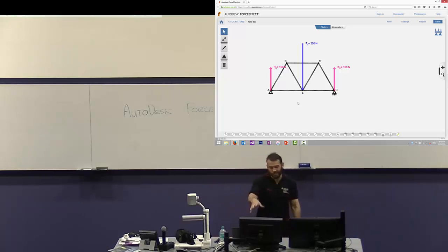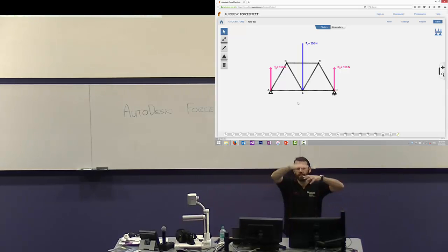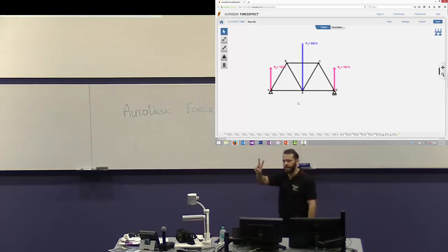So through this, obviously this is a really simple bridge design and you've only got a couple of members and only two different forces. But if you've got a really complex design and some members are long and some members are short and it goes all over the place, what this gives you is which is my critical member, or where is the largest force. And that's both on that member and the pins or the glue or whatever that's holding it.